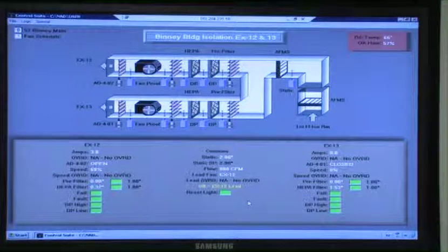So if one of them fails and the other one starts, you're gonna end up rat racing a lot of your air. We spoke about this in the past: the sequence called for the damper to close on the one that failed. Well, the thing that starts the fan is that the damper is open. So in order to shut the damper if it fails, I have to lock the alarm in place to close the damper, because I have to shut the fan off.